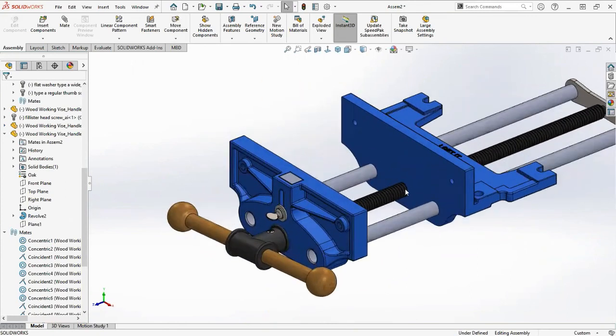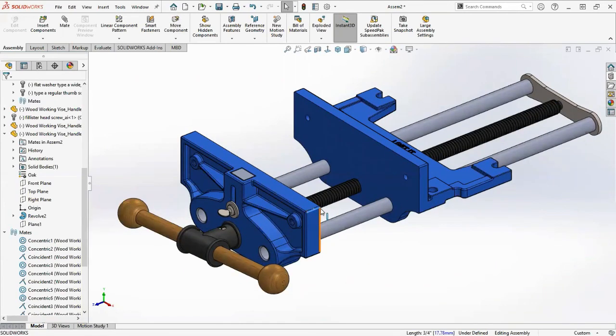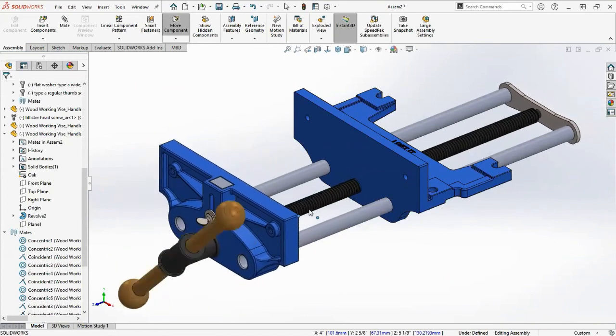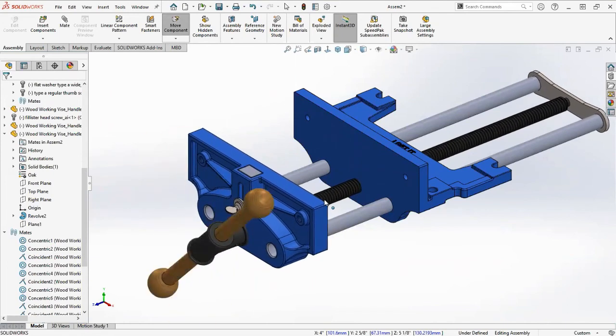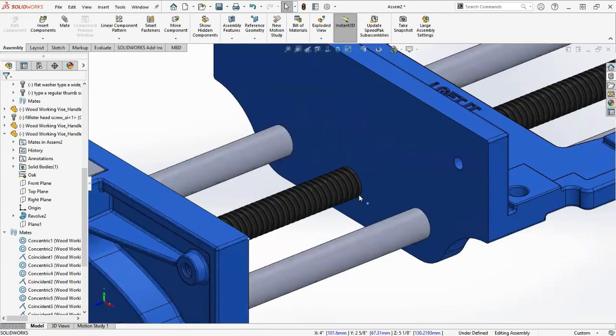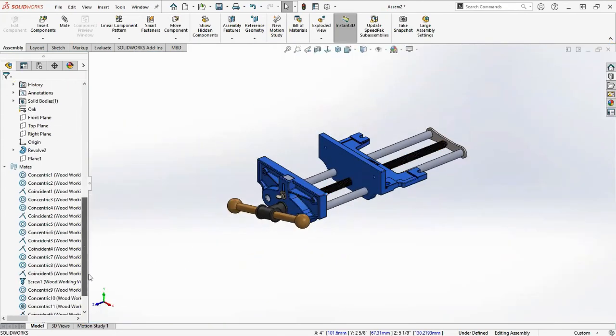The last thing we're noticing is that this screw profile should appear as if it's standing still if it was set to the right setting. But instead you see the profile moving through the part there. So we need to adjust our mate, our screw mate, to correctly represent that